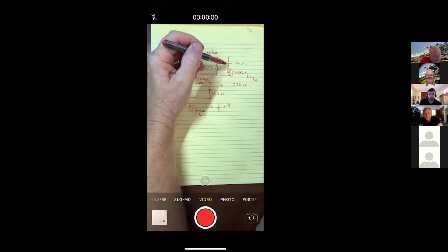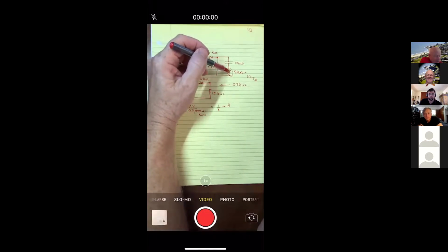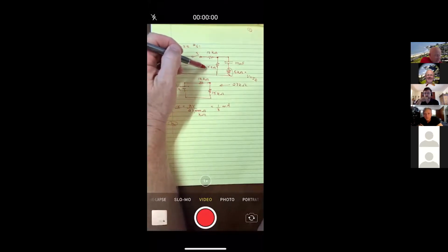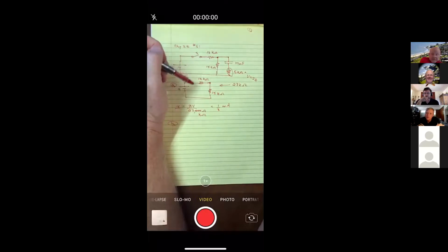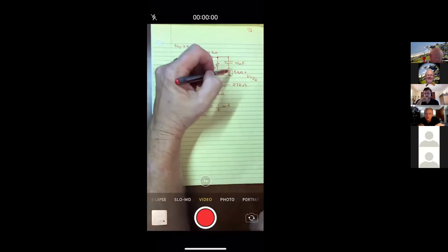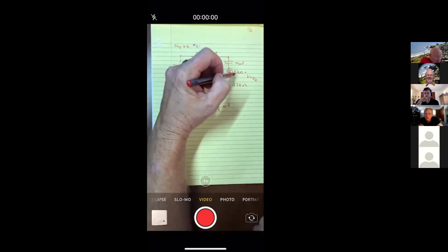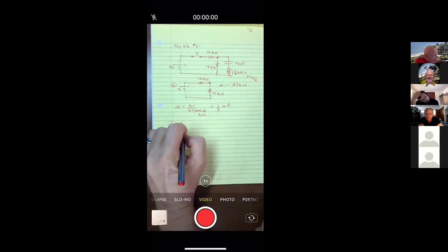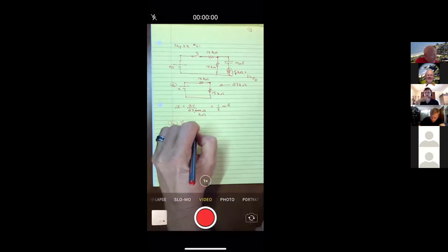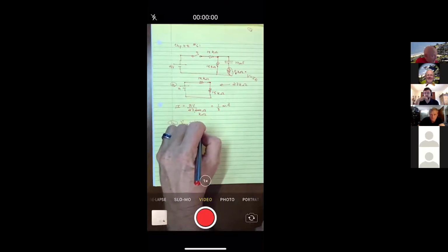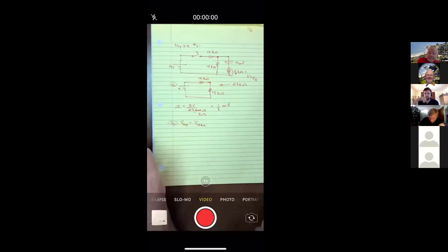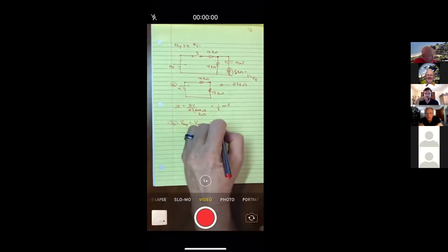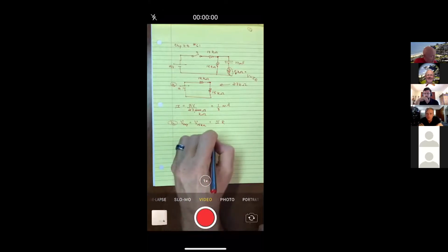Now, I guess I would say that the voltage on the capacitor and the voltage on this resistor are in parallel, so they would have to add up. The voltage on these two have to be the same as the voltage on this 15 kilo ohm resistor. But as I just said, there is no voltage across this 5K because there's no current there. So what I'm trying to say is the voltage on the capacitor is the same as the voltage on the 15 kilo ohm resistor. And that's pretty easy to calculate because it is just Ohm's law, current times resistance.